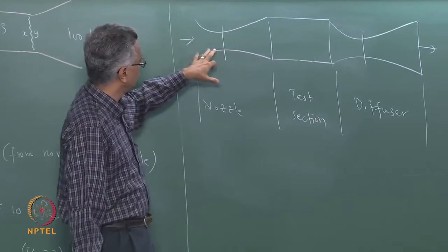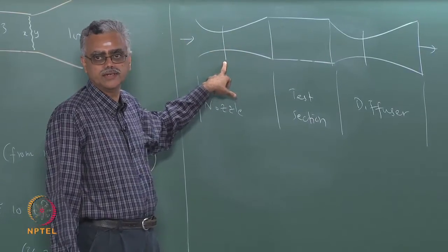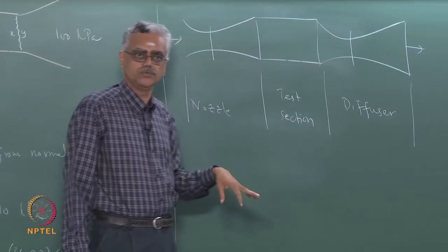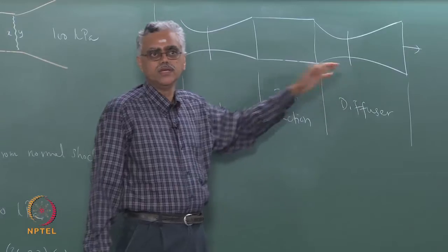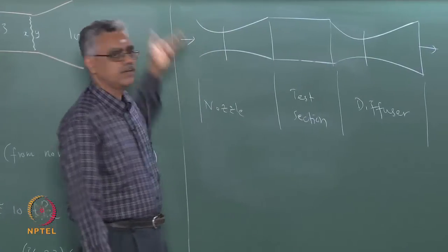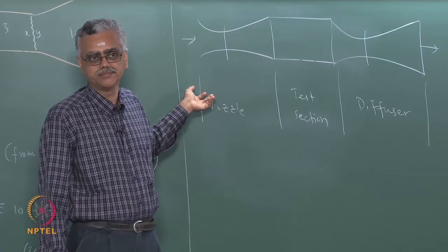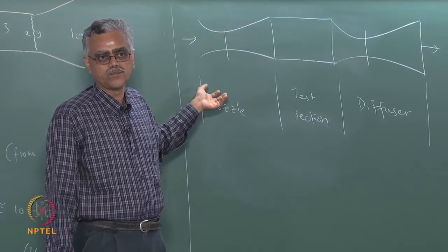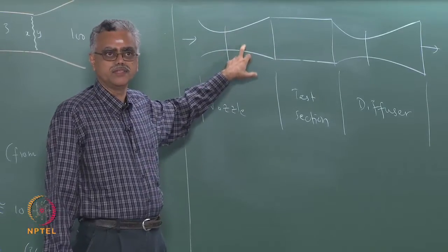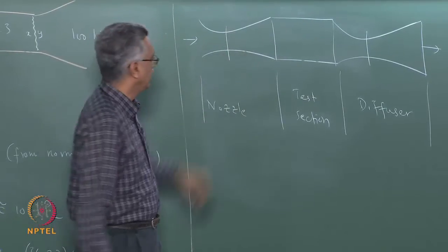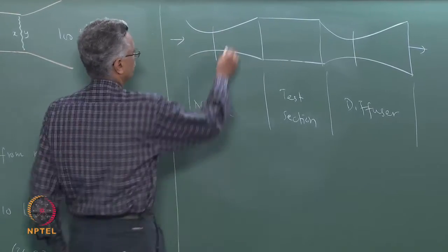I now set up a situation where the flow accelerates, M becomes equal to 1 here, right, and then again subsonic flow throughout, perhaps M becoming equal to 1 here maybe. Now, if I crank up the stagnation pressure a little bit more, what happens next? I have a normal shock, right, somewhere here. I set up a normal shock somewhere here, and once I set up a normal shock here, the mass flow rate that comes through this,